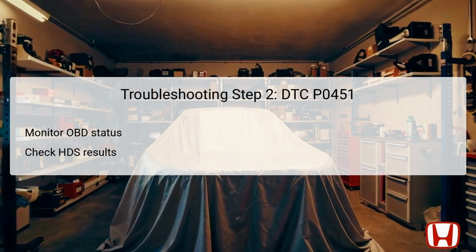In the second troubleshooting step, utilize the HDS to monitor the onboard diagnostics OBD status for DTC P0451. The diagnostic system will provide insights into the status of the FTP sensor circuit, indicating whether the test result is failed, passed, or not completed. If the system indicates failed, it implies that immediate action is necessary, namely, replacing the FTP sensor, since it has confirmed a failure in the circuit.